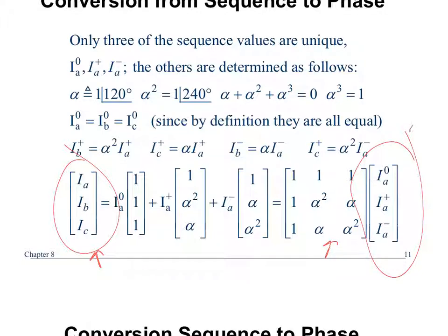I can calculate the symmetrical components as long as I have 3 currents to measure. I know what this matrix is here. It's not going to change, right? And it does not change. That's fixed. Then I can get all the symmetrical components.